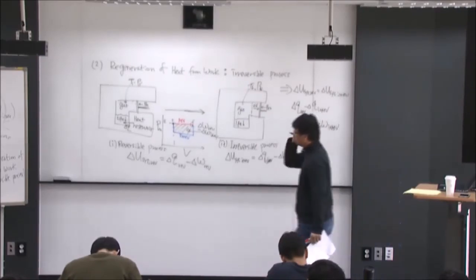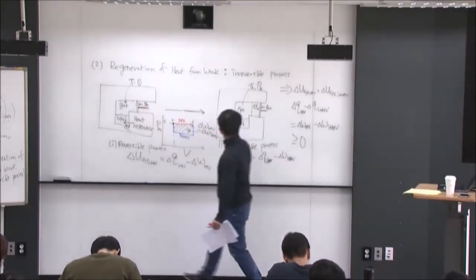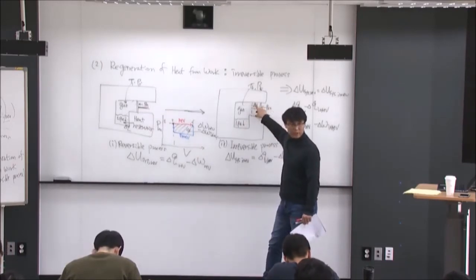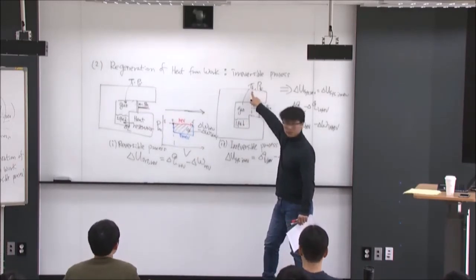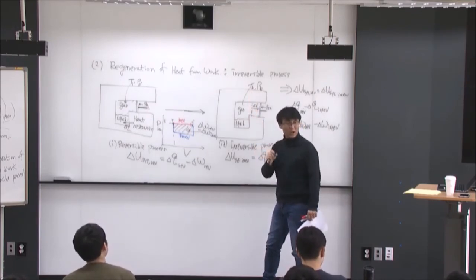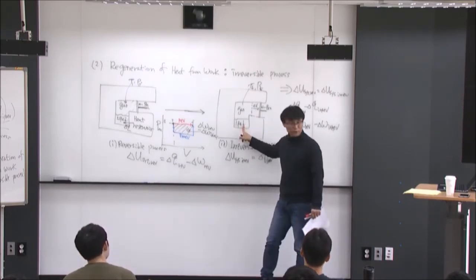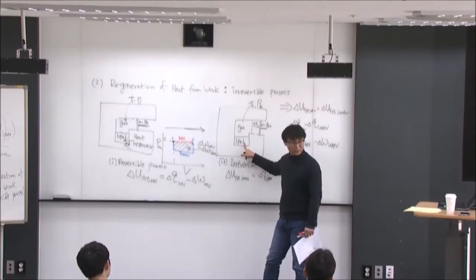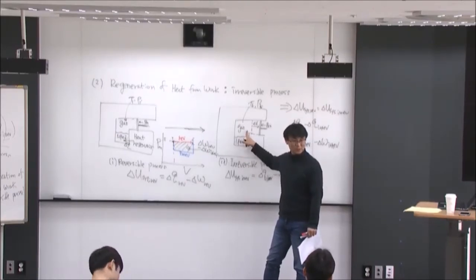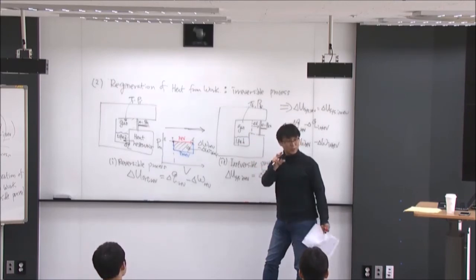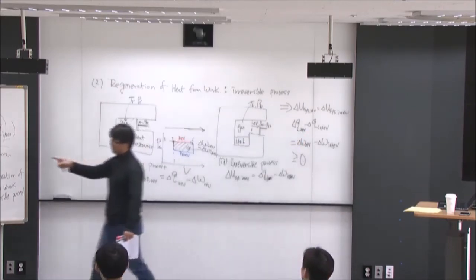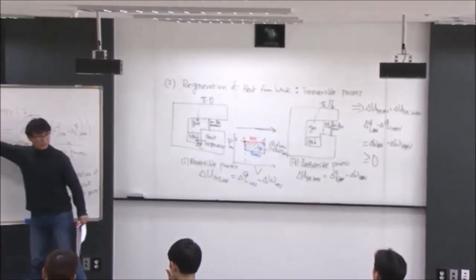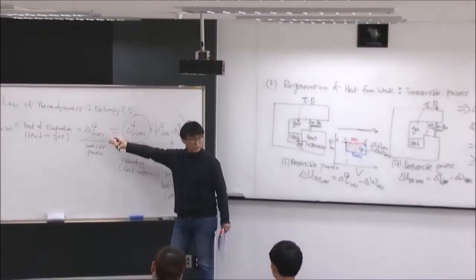One more time. Okay. Let's assume this way. Because of the expansion of this volume, PV equals nRT, we know the P, the T, and the V, so we can calculate how many moles of gas should be evaporated. Let's assume I have 0.5 moles of water that should be evaporated, from 25 degrees to 25 degrees of the gas phase, or 100 degrees to 100 degrees, for example. Then in order to evaporate that, I need a certain amount of energy. That amount of energy we just define as this one: the heat of evaporation, the total heat I need in the system.